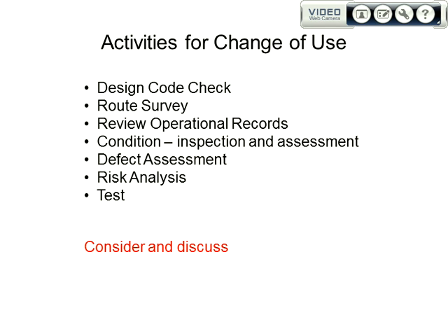And you're going to have to consider, because you're changing the use of a pipeline, normally that would be seen as the start of a new design life. New design lives normally start with a test. If you're complying with codes to the letter, you would say, right, well, we need to retest. So you need to say, do you really need to retest? Because I promise you, pipeline operators will never retest a pipeline if they don't have to. So there's got to be a very good reason for that.